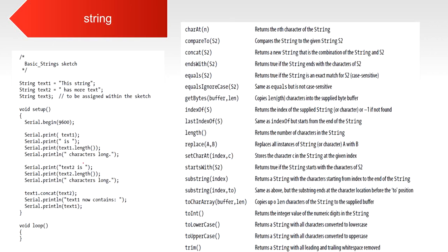The next part is one of the important aspects in developing a serial communication protocol: how we can create a function that can handshake between two microcontrollers, or between a PC and a microcontroller. Now it is based on string manipulation. It means that the PC will send some command in string form, and later the Arduino can decode it accordingly.